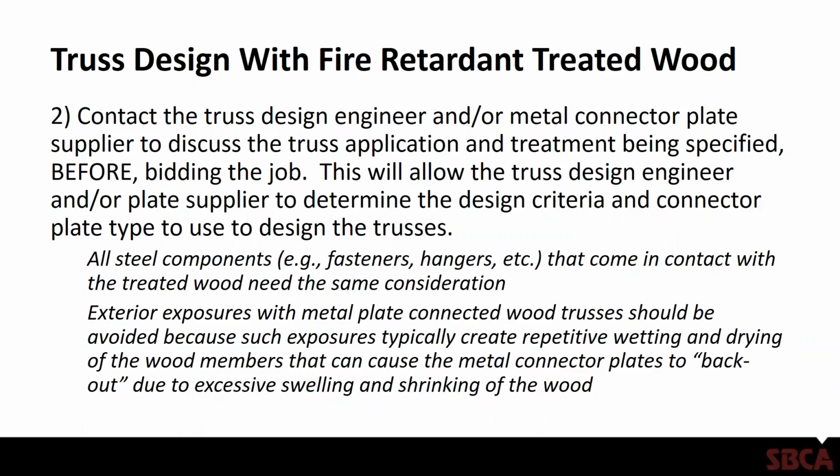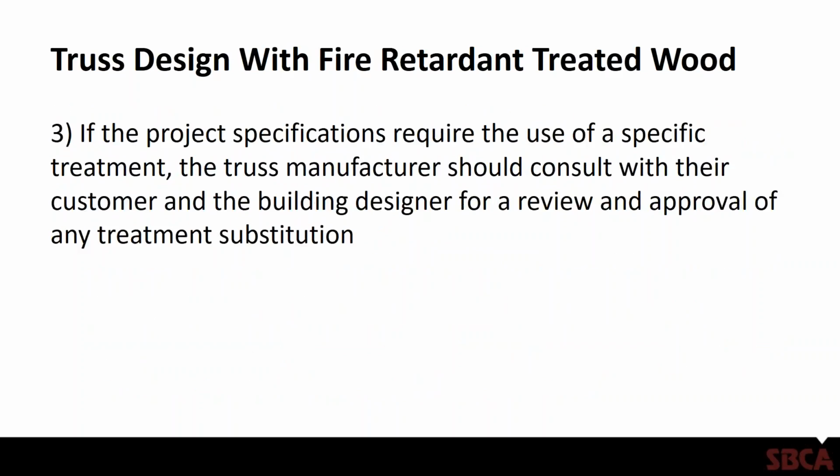Since most of the connector plates used today have a tooth length of only about 3/8 of an inch to 7/16 of an inch, that's why exterior exposures really are not a very good idea with metal plate connected wood trusses. A couple more items here and I'm done.